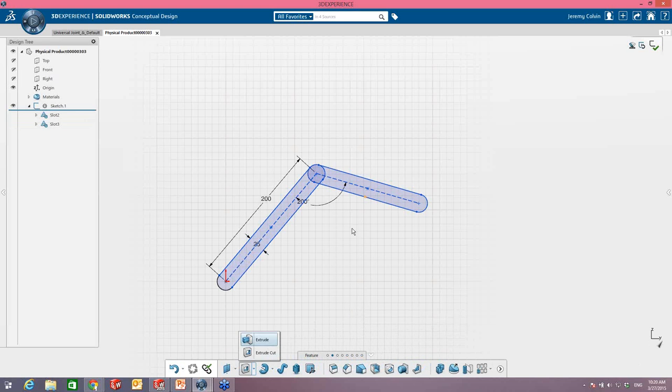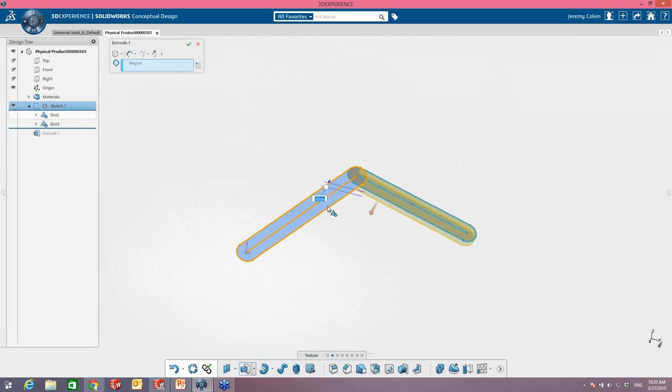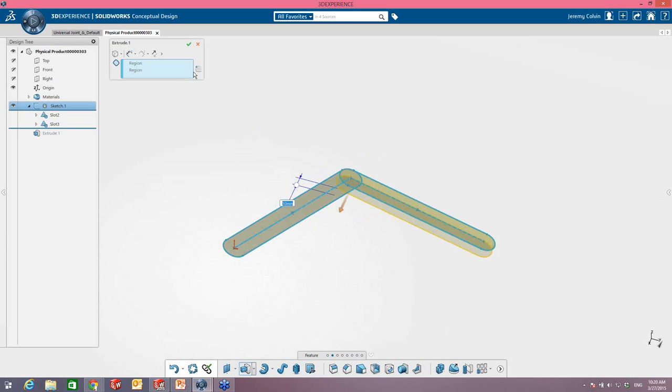So selecting the extrude cut and just picking on this feature there, you can see it's going to extrude that. And I can grab that part as well, just to make that more complete. The interface you see on the extrudes up here is where we can actually select solid, thin, or surface options. We can see the options to select it blindly or mid-plane or up to geometry, up to other geometries in the model. We can flip direction, of course, or as some of you know in SolidWorks as well, you can just grab and you get the rulers available to us up here on the screen.